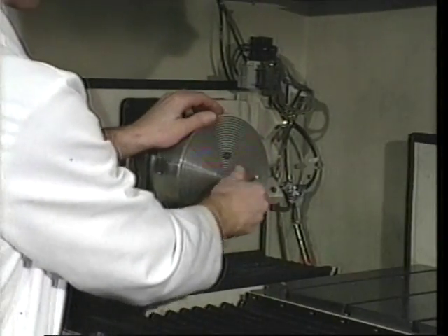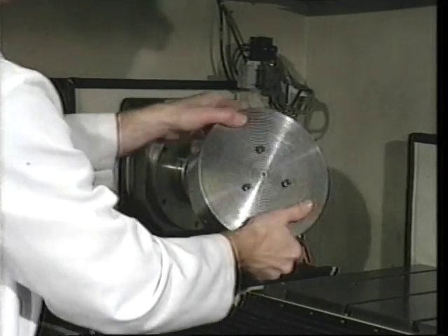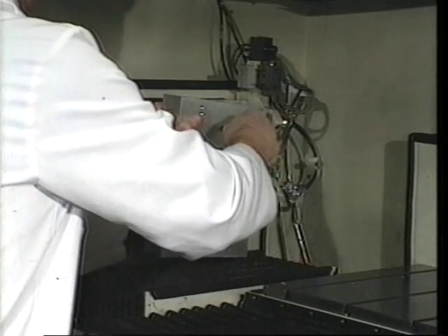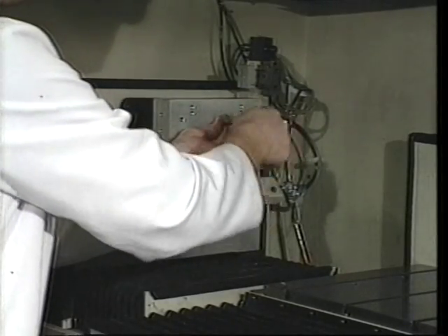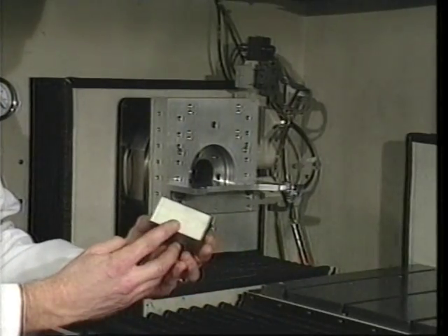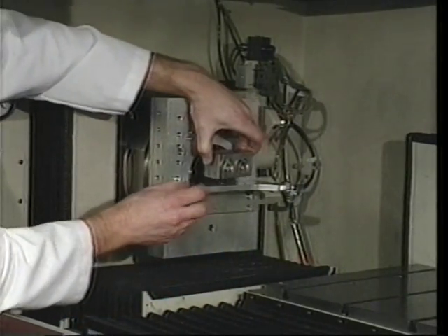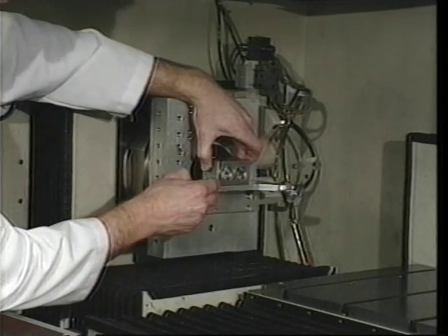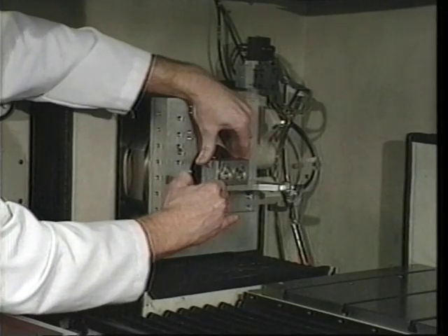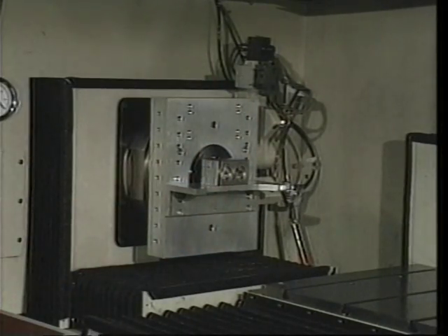In preparation for these measurements, the spindle's vacuum chuck is removed and a special mounting plate is attached to the housing of the spindle's air bearing. Using double-sided adhesive tape, the angular reflector is mounted to the angle support on the mounting plate. Note that the reflector is positioned so that the retroreflectors are facing out, that is, away from the spindle. Here, the reflector is horizontally positioned for making yaw measurements. If pitch measurements were being performed, the reflector would be positioned vertically.